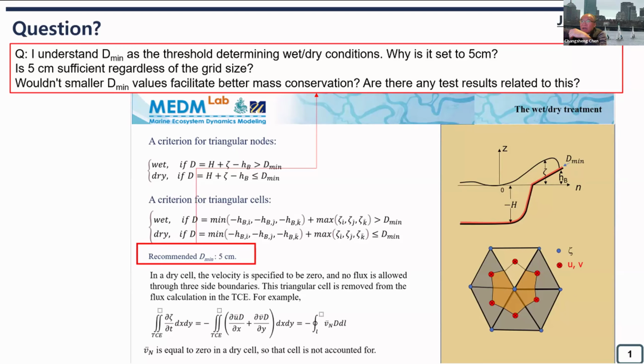Water should be advected into your wet point, right? But the problem is that with a flux boundary condition equal to 0 at the boundary, you cannot get the exact calculation of the water getting back to the wet point. That's why you get some kind of leaking of water in your model.